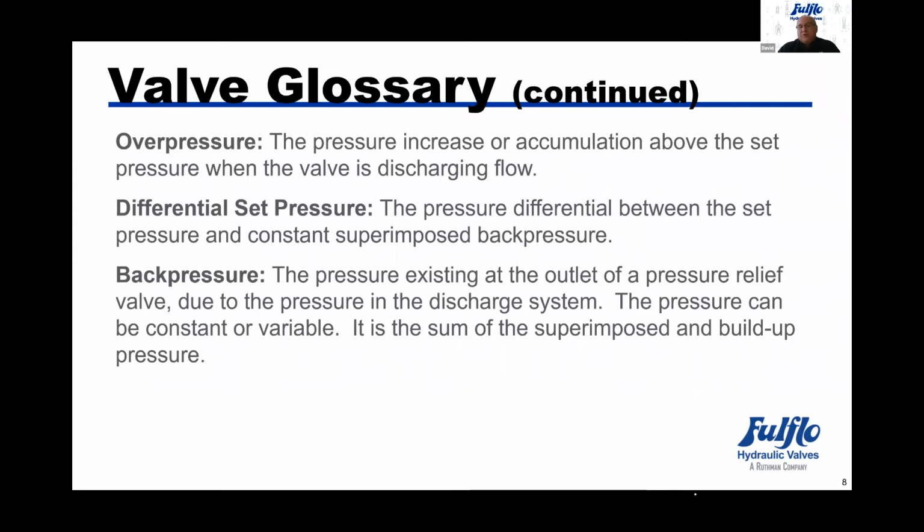Where back pressure is just the pressure that's affecting the discharge side of the relief valve due to the pressure in the system. That could be the constant or the variable. So it's a sum of the buildup of pressures.